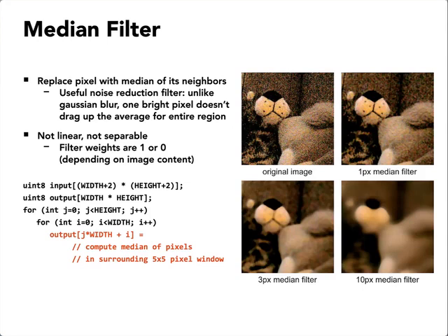So you can imagine how you can put sophisticated nonlinear image processing or nonlinear computations inside the inner loop of these filter operations, and in general compute functions over the neighborhood of values in the filter kernel neighborhood on the input image, the median filter being one example. Oftentimes that can get very powerful, but very computationally expensive very quickly.